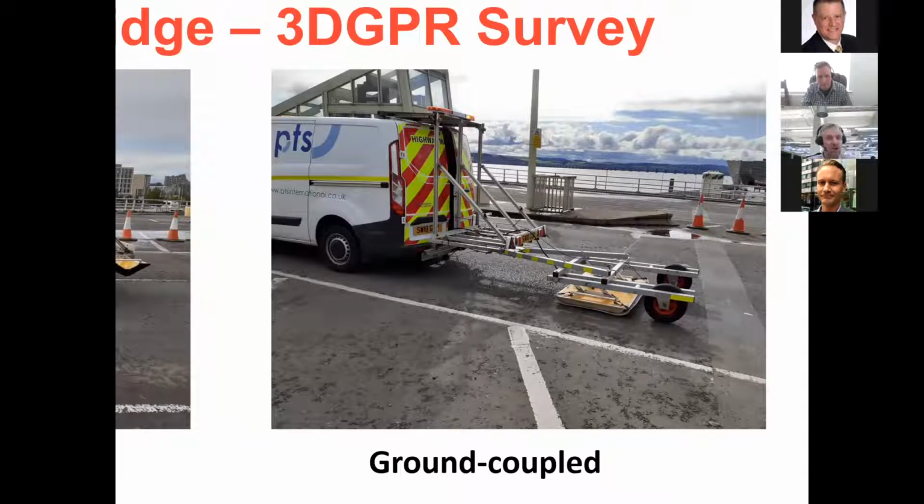Also, we've got the dwell time, so we have to be careful of that. And the spacing that we'd set up in the system that we would scan. In this particular case, it was scanning every, I think, about 8 or 9 centimeters. So that's why you'll see the reinforcement will look a wee bit closer. But that's what we were doing.